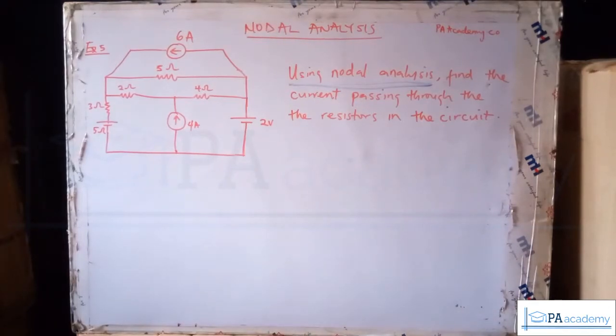So if you have been following so far since the beginning, if you have watched the last 4 examples, you can just pause this video and use this one to test your knowledge on what you've learned so far in the course of this video under nodal analysis. So don't forget the steps. Once you have a question, you try to identify how many nodes there are. You pick a reference node, you pick your current direction, and then you apply Kirchhoff current law. Alright, so just pause the video and attempt it, and then use that to test your understanding.